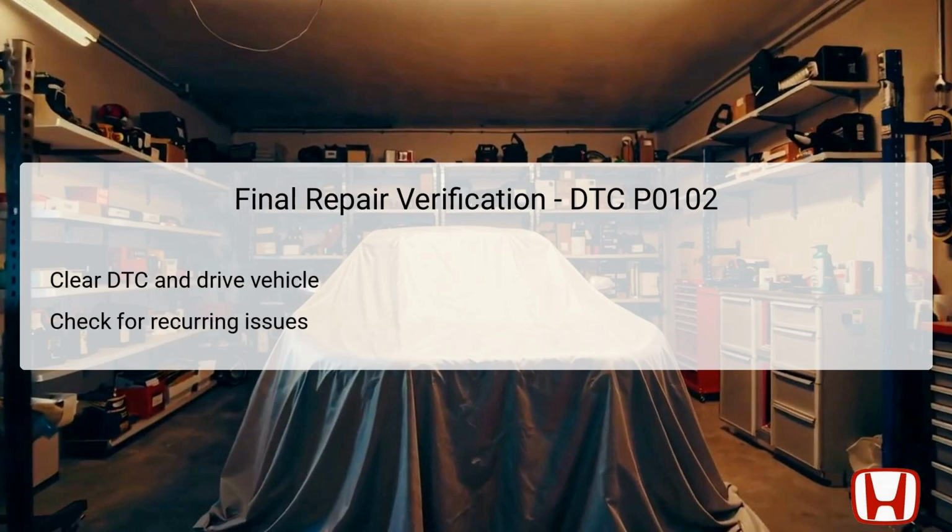Once repairs have been completed, it is important to clear the DTC using a scan tool to reset the engine control module. After clearing the code, take the vehicle for a test drive to validate that the problem has been successfully resolved.